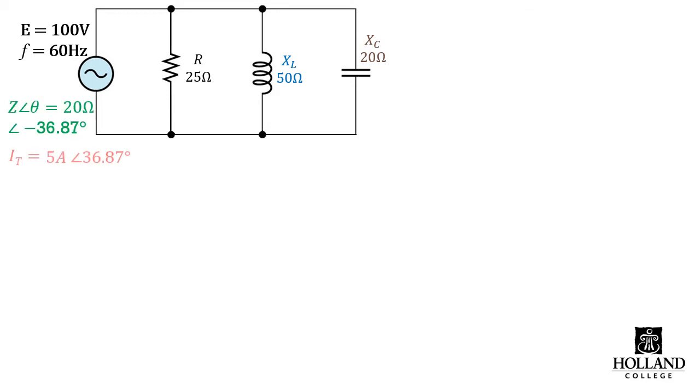In our previous slide, we calculated out the impedance using an impedance triangle. Since impedances are a reciprocal vector sum, it can be a bit of a challenge. Not impossible, just challenging. And we ended up with 20 ohms and 5 amps. But when we reflect back on our parallel tenets, current adds nicely. It's still a vector sum, but we don't have to worry about all the reciprocals. So let's use current to calculate out our Z impedance.